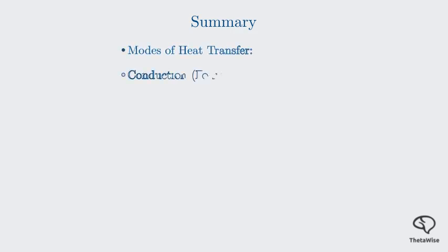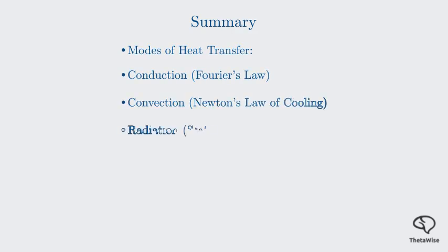We have covered a significant amount of material on heat transfer and heat exchangers. Let's summarize the key concepts we've explored. We began with the fundamentals, the three modes of heat transfer: conduction through direct contact, convection through fluid motion, and radiation through electromagnetic waves. We learned how to model these modes using Fourier's law, Newton's law of cooling, and the Stefan Boltzmann law, and how to combine them into powerful thermal resistance networks.